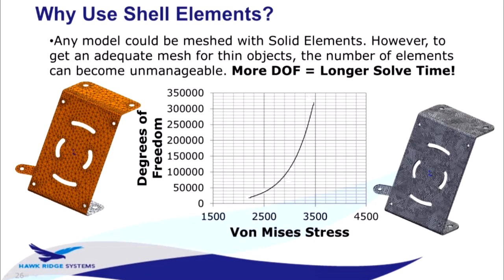So, one quick question is, why do we use shell elements? Well, for something that is thin geometry, it can be really challenging to map a 3D element through the thickness, especially if that thickness dimension is significantly thinner than the span dimensions in the other aspects. And so we can end up with enormous amounts of mesh and still not accurately capture maybe the bending stress. We talk about needing 2 solid elements through every thickness of a part in order to accurately capture bending stress. And that can just be not feasible with thin components.